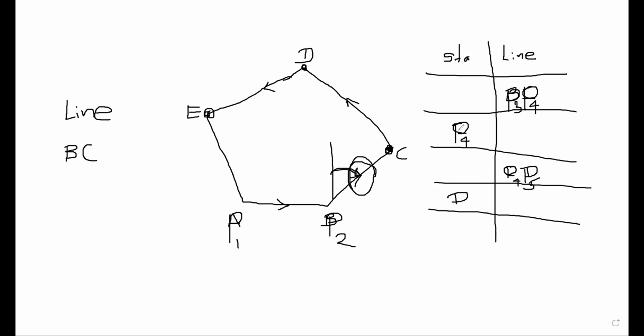It is recommended, when you put these notations for your own survey network, please put them in anti-clockwise order. A, B, C, D, or 1, 2, 3, 4 doesn't matter, but maintain some order, because that way will make the calculation easy. So you will not get many mistakes, because after that we are just following the table, so it is easy.